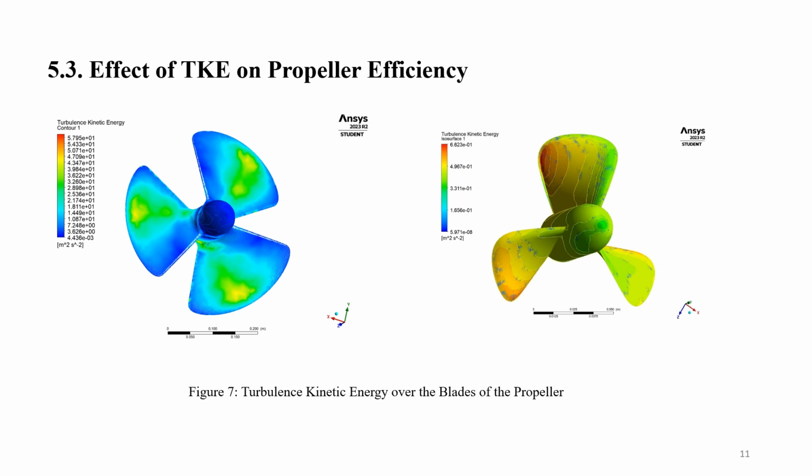To gain deeper insights into the distribution and intensity of turbulence kinetic energy around the propeller blades, Figure 9 and Figure 10 provide a contour visualization of the turbulent kinetic energy on the propeller for both conditions. Both figures showcase that the trailing section of the blade experiences the maximum turbulent kinetic energy, contributing to the formation of excessive low pressure zones due to pressure fluctuation.